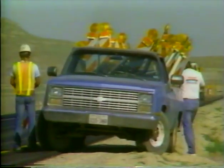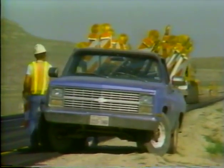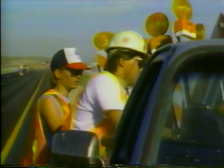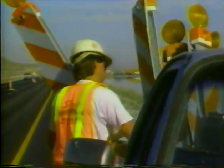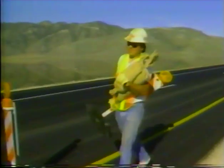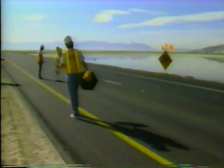Flashing lights on barricades are good devices for drawing attention to isolated hazards. But for delineation, you'd use steady burning lights that outline the safe travel path. The point is, the contractor must use the signs and devices specified, not what he happens to have on the truck. The devices must be made of approved materials, and they must meet the minimum standards of size, design, and color described in the MUTCD or called for in the plans. And that's all there is to selection.